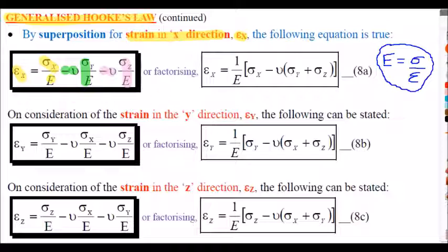All I've done here is just factorize because the elastic modulus is common, because we're assuming isotropic and homogeneous materials, then the elastic modulus is common. I've just factorized on the E, on the right-hand side equation. Same equation, just factorized. I've also factorized on the 2 mu terms here, where I've got my Poisson's ratio. Again, I've factorized on those. So it's just a factorized form on the right-hand side. I tend to use the left-hand equation in my calculation. I think it's more explicit to what we're actually doing. But the right-hand equation is just a factorized form.